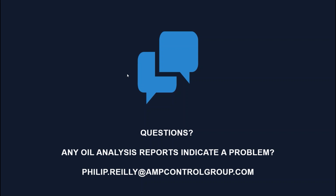Question: is stray gassing more prevalent in certain makes and designs of transformers? So this is low temperature heating of the oil, and certainly we do see in newer transformers of the sealed type, more distribution size, we do see some more low temperature overheating, which may be a consequence of the design of the transformer. So yes.